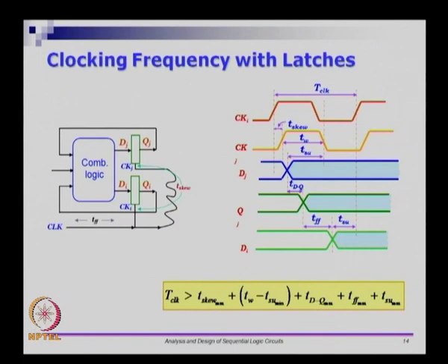So, this brings me to the end of module 33, and in this module we looked at timing analysis of both latches and flip flops. So, the most important thing for the latches and flip flops is what is the frequency at which you can run, and for flip flops is there a setup violation. Sometimes you are also interested in hold violations. For latches, again setup and hold violations.